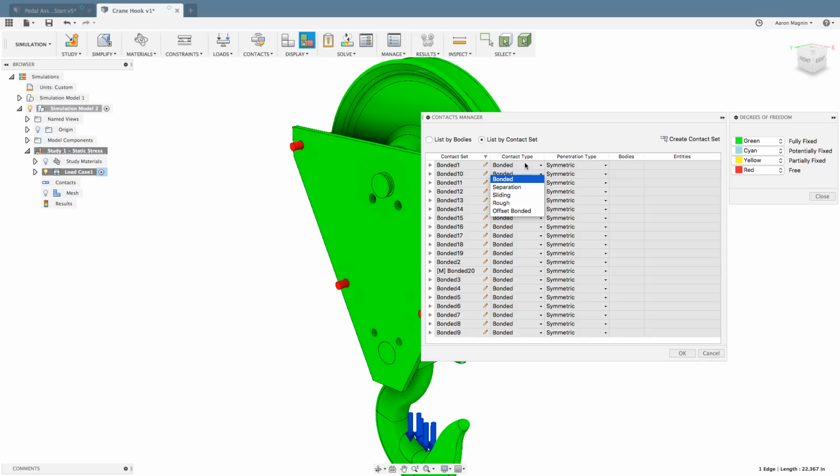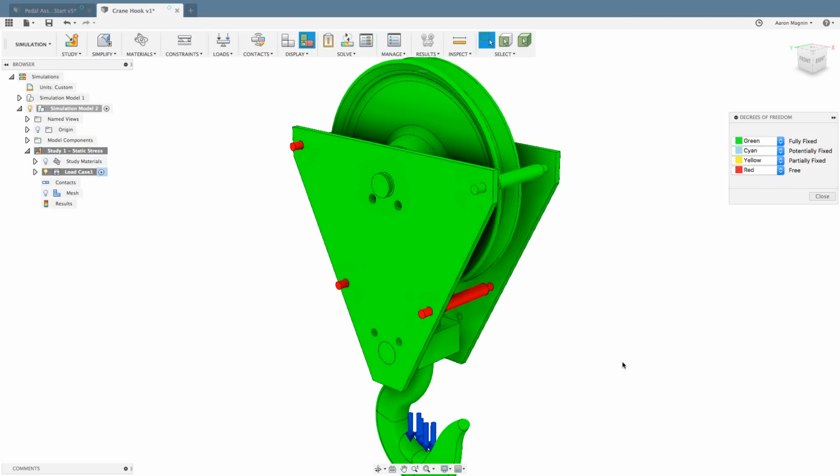When you do things like separation and sliding, it's a much more complex analysis, and it's a lot more mathematics that's going on there. Anyway, I do not want to do that 7 more times. I mean, although this is green, it's not connected on the back face there. So the reason why it's green is that there's a connection somehow going through this to connect that, but really it doesn't know that this face is touching this face. So it's a little bit misleading. I mean, if you solved it and you looked at the results, you could tell right away.